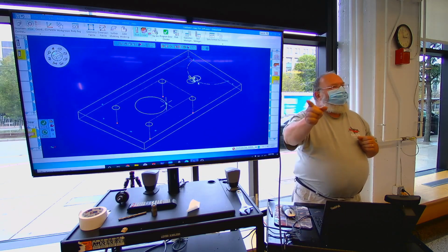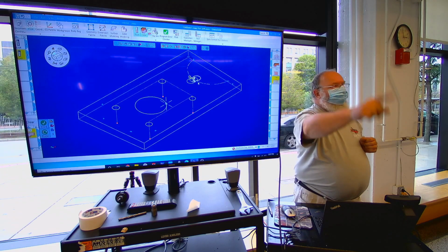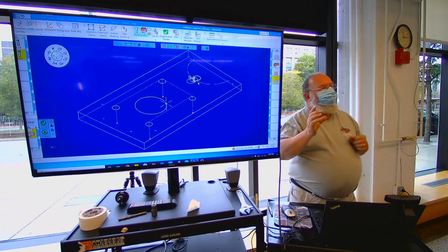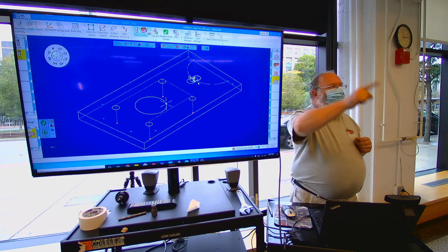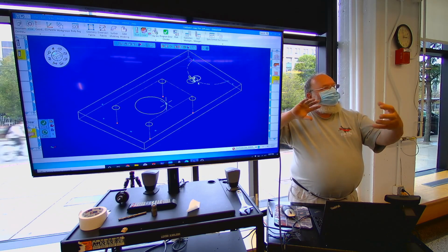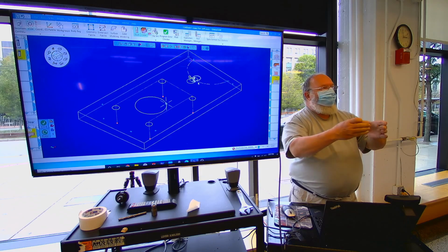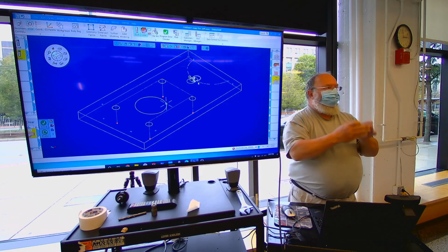The male portion of the ball screw is a hemispheric helical groove. The nut portion is a helical row of ball bearings that match the groove. But what it allows us to do is to pre-tension the ball bearings to virtually eliminate all of that end play between the nut and the screw.